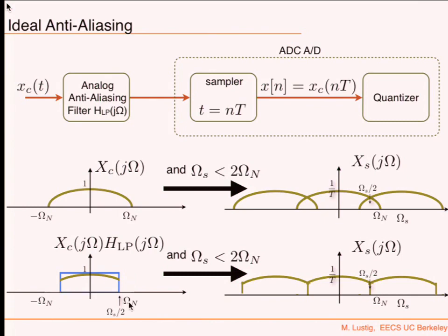There's going to be some roll-off in any real system, and that roll-off means that there is going to be some aliasing. I showed it to you when we did this SDR. We assume we get 2.4 megahertz of bandwidth, but in fact, the edges of this bandwidth are contaminated by some aliasing due to the anti-aliasing filter not being perfect.